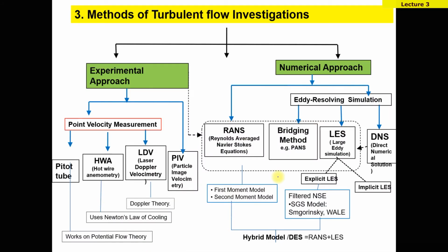Then methods of turbulent flow investigation. There are some experimental techniques or numerical techniques. This is the experimental technique, which is divided based on point velocity measurement. It's called Pitot tube, which is based on potential flow theory, but it doesn't capture the fluctuation.